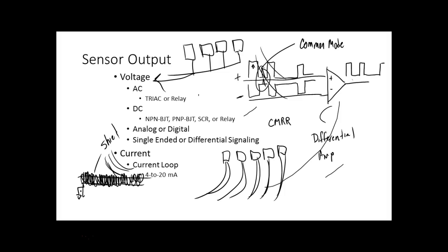So these are just some basic terms we'll be looking at. All our sensors are going to be similar, but they'll probably be shielded, right? Understand that? Makes sense, huh? So a shield, by the way, guys, no matter what you're told, should only be grounded on one side. If you ground it on both sides, it becomes a conductor. We want it to be an antenna. We want it to grab the EMI and send it to ground. We don't want it to be a conductor. So a shield should only be grounded on one side. We'll look at some Ethernet switches that we got in the metal over there that are designed to do this.